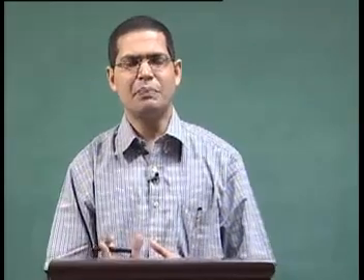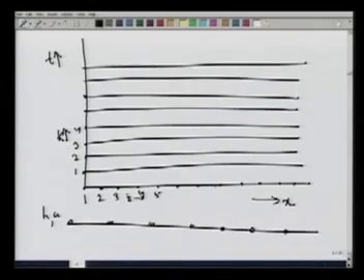But the dependent variables, the unknowns, are the flow variables u and h, the velocity and the flow depth. So at all the nodes I need to find out what is h and what is u, what is h and what is u, like this. So for all the nodes and also at all the time levels I need to know how h and u vary.